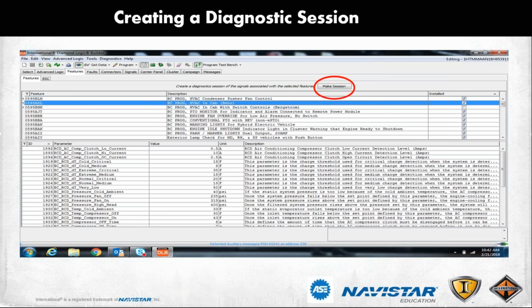So once again, look in the upper right-hand corner, we make sure we're in diagnosing mode for this. And you're going to look at all the signals. So the top line depicts AC clutch. In the pins column, we see it is on connector 1603, pin C. And it's called a digital output because it's either on or it's off. So in this case, it has a box there. So when the box is empty, that's off. When the box has a check mark in it, then that's signal, whatever it is on.